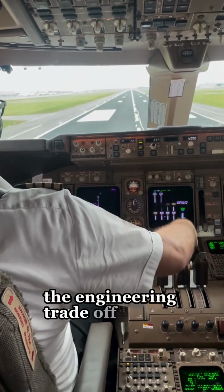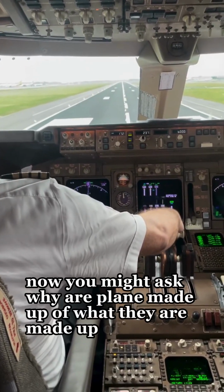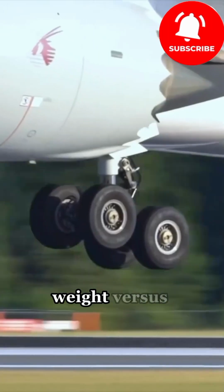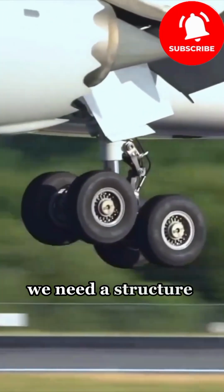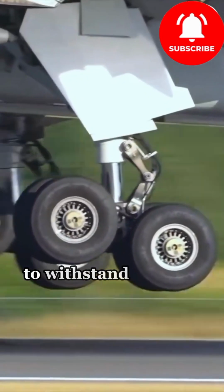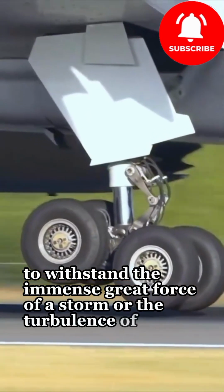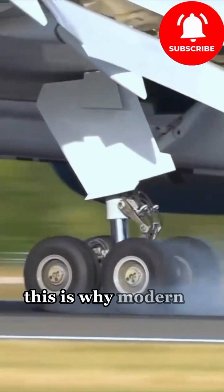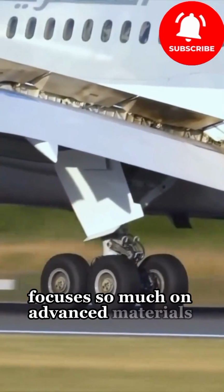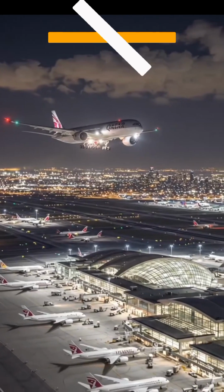The engineering trade-off. Now you might ask, why are planes made up of what they are made up of? It is the ultimate engineering trade-off. Weight versus strength. We need a structure light enough to get off the ground, but strong enough to withstand the immense G-force of a turn or the turbulence of a storm. This is why modern airplane engineering focuses so much on advanced materials like carbon composites, not just heavy metals.